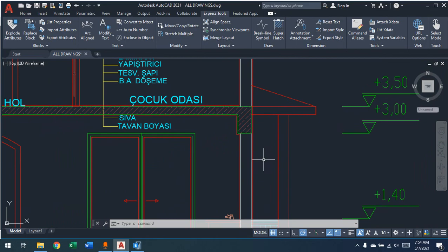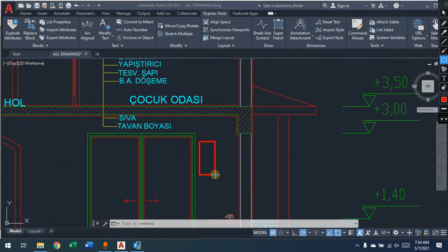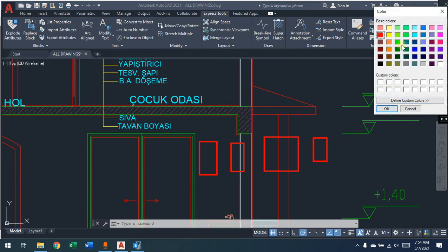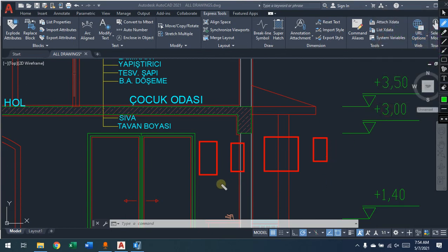This is something we have in Etabs. It can go through the list of sections. Let's say you provide some sections to Etabs. You'll say, okay, let's have a section like this, another section like this, one half like this. You will give a lot of sections to Etabs, and you will tell Etabs to choose from those which one is appropriate for this beam. You will let Etabs choose which one is appropriate. Yes, it's possible.